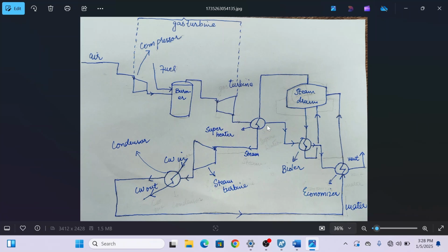So you have to add all these delta P's and place a value over here that is above that sum, and this value must be above the atmospheric pressure, because if you specify 1 bar here, after passing these three heat exchangers there will be a pressure drop, and the pressure here becomes 0.9 bar.